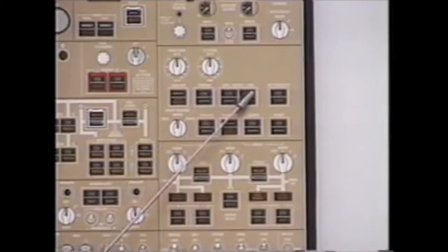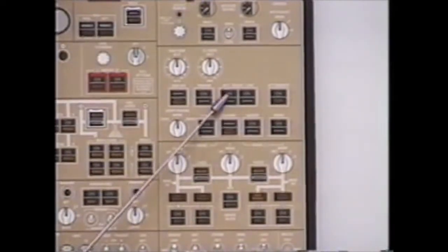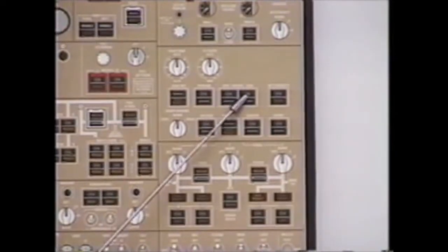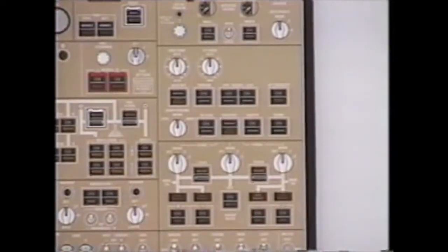Upper and lower recirc fans. The upper fans will always run as long as the switch is on. The lower fans will run when the packs are in normal flow, which should occur shortly after top of climb. Aircraft trim air uses hot air off the center manifold to mix with cool air leaving the packs to adjust compartment temperatures to selected levels. Turning off the trim air will cause all three air conditioning packs to put out a temperature that keeps the temperature of the compartment at an average of 75 degrees.